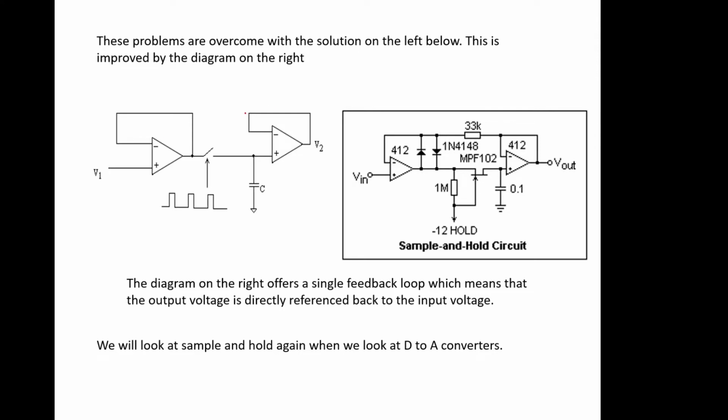If we've got a single loop around here, all the way around, and we break the loop here, then what's going to try to happen is that this op-amp will try to maintain 0 volts between its inputs, which would normally be a nice closed loop system. It's now open, so whatever it does here, it's going to run into grief if this signal moves around.